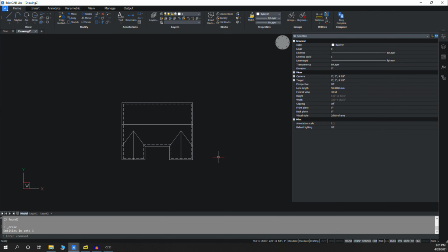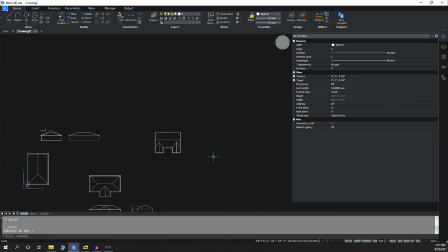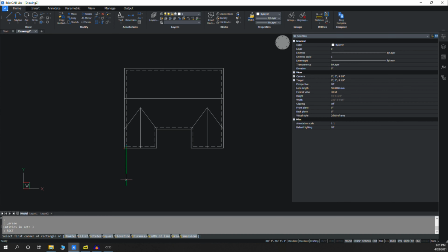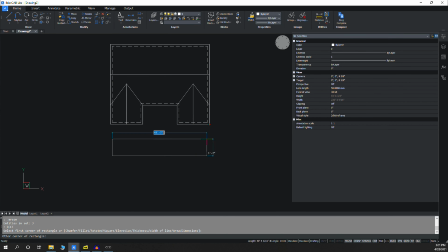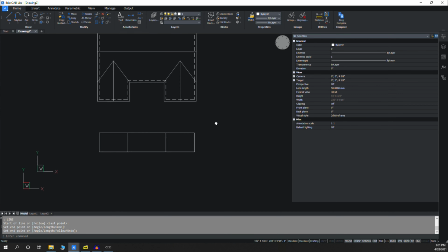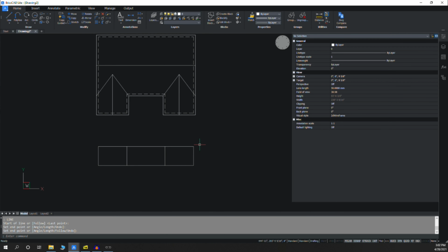We've got the roof in plan. Let's drop the elevations really quick, and we're going to use measuring sticks to get all the weird angles and stuff like that. So I'm going to draw a rectangle for the size of the house. I don't remember how long the house is, and I don't need to. I'm just going to pick up that point. And it's 10 foot tall. And we'll draw in our gable ends from the front here. And we need to remember to include our 12-inch eaves this time.